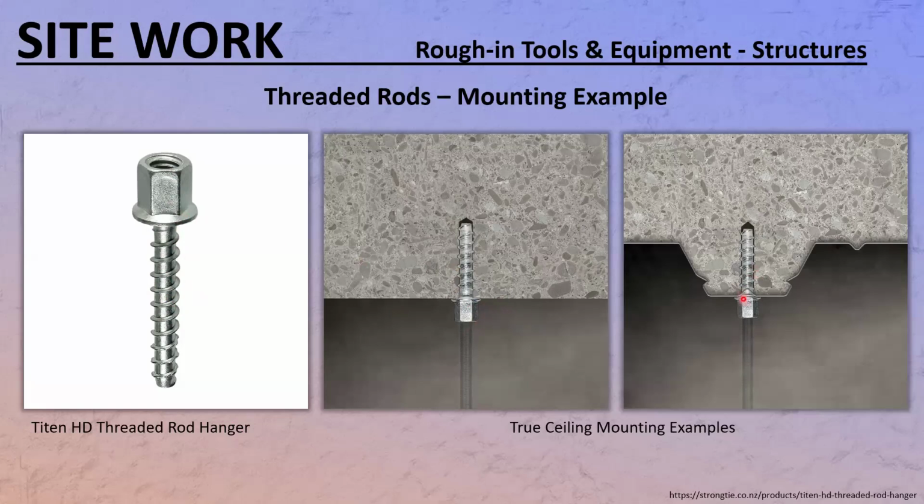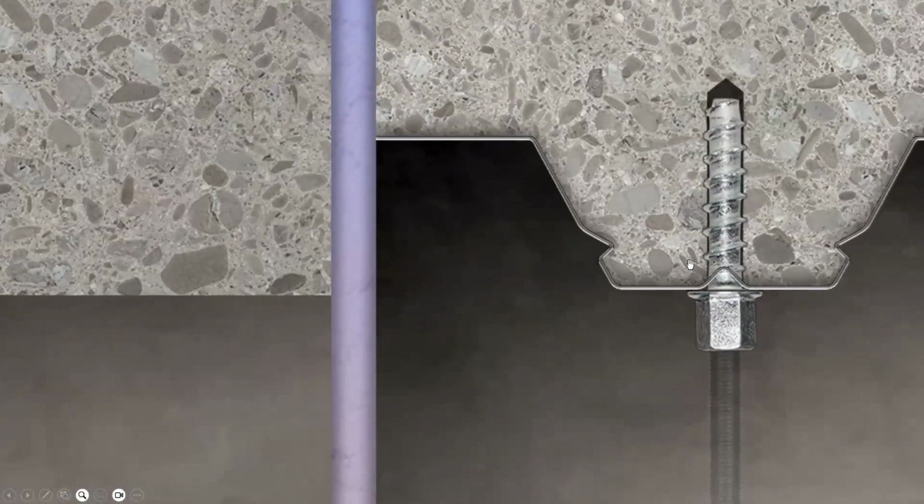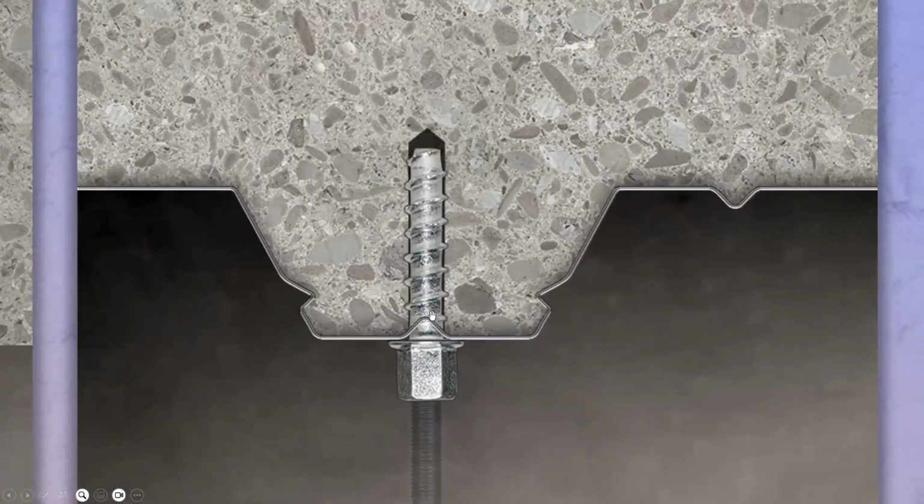The problem sometimes is when you have those perforated steel ceilings, where there is a layer of steel finishing off the concrete, so there's not bare concrete, there's a layer of steel you have to go through. That makes the job a heck of a lot longer, and you go through a lot of drill bits.